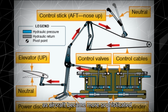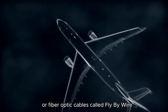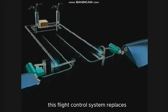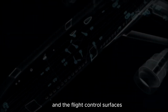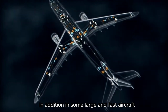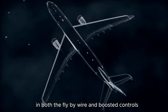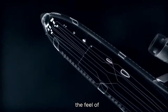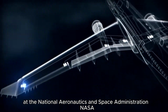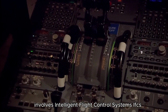As aircraft became more sophisticated, the control surfaces were actuated by electric motors, digital computers, or fiber optic cables. Called fly-by-wire, this flight control system replaces the physical connection between pilot controls and the flight control surfaces with an electrical interface. In addition, in some large and fast aircraft, controls are boosted by hydraulically or electrically actuated systems. In both the fly-by-wire and boosted controls, the feel of the control reaction is fed back to the pilot by simulated means. Current research at the National Aeronautics and Space Administration (NASA) involves Intelligent Flight Control Systems (IFCS).